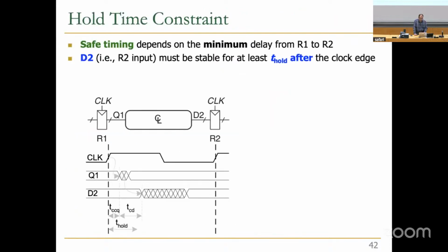Now let's take a look at the hold time constraint. For hold time, we want to make sure that our D2 stays stable after the rising edge of the clock, at least for T hold.